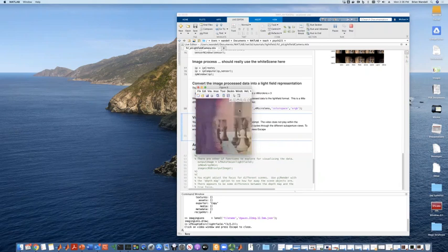The other thing, you can see this weird purple stuff that's floating around there. That's an indicator that, as you move off to the edge of the micro lens, not every subaperture view is actually that good. Some of them are noisy. Not that much light gets there, or if light gets there, it mostly stimulates one type of sensor compared to the other, the red versus the green versus the blue. So we're looking at a little video showing the subapertures individually, and that, in a way, is the information that we have to work with to create all the modified views, the refocused views, or depth estimates and so forth.